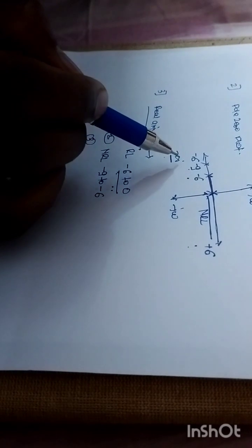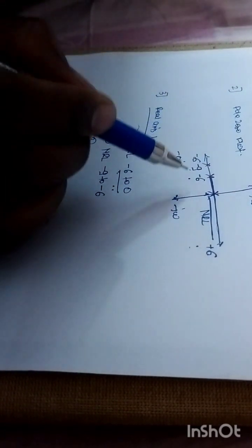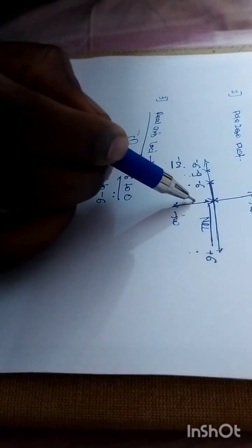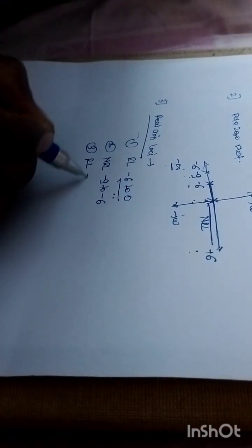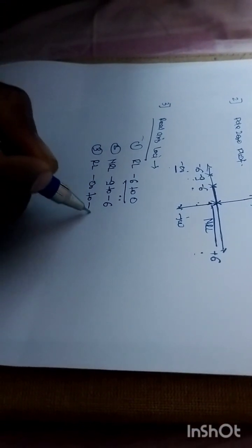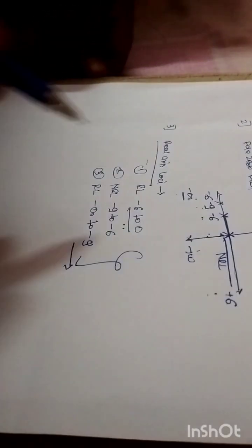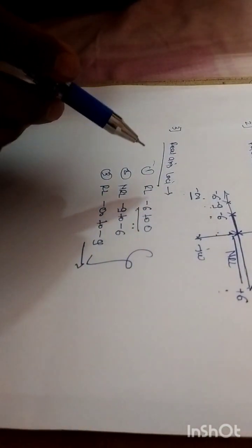So to the right hand side of this pole, which is located at minus infinity, we have 3 different poles, located at 0, -6 and -9, meaning the root locus is present in between minus infinity to -9. So in this way, in this step, what we need to determine? The real axis loci. This is the step number 3, right?